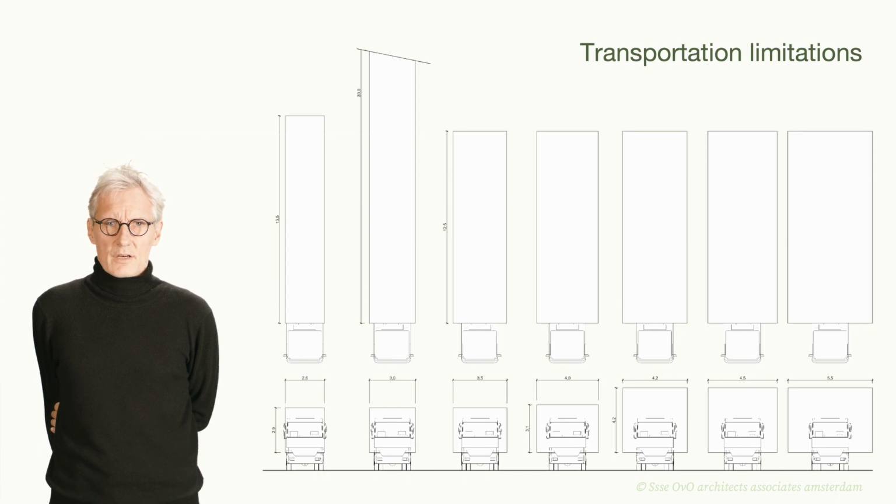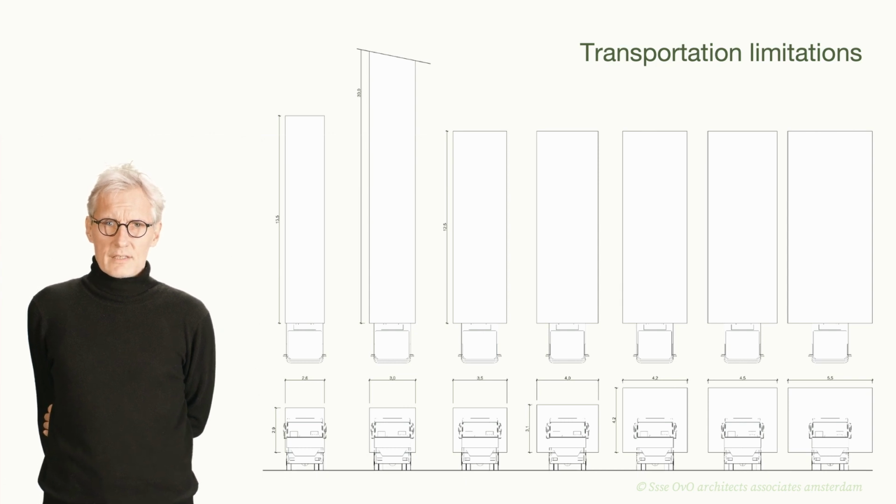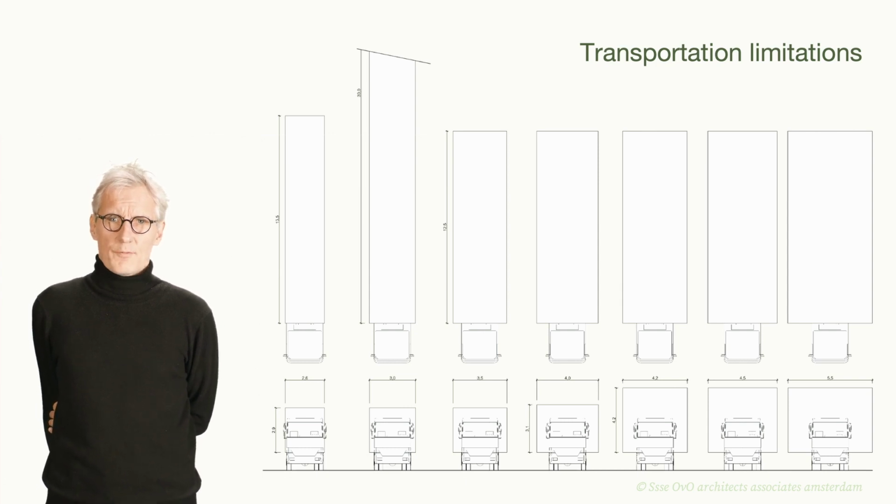Transportation can also be a constraint for the module dimensions and leads to the design being often restricted to the module's box-like form. Another concern is that the stiffness needed for the modules during transport could be higher than the building actually requires, causing a potential overdimensioning of material.